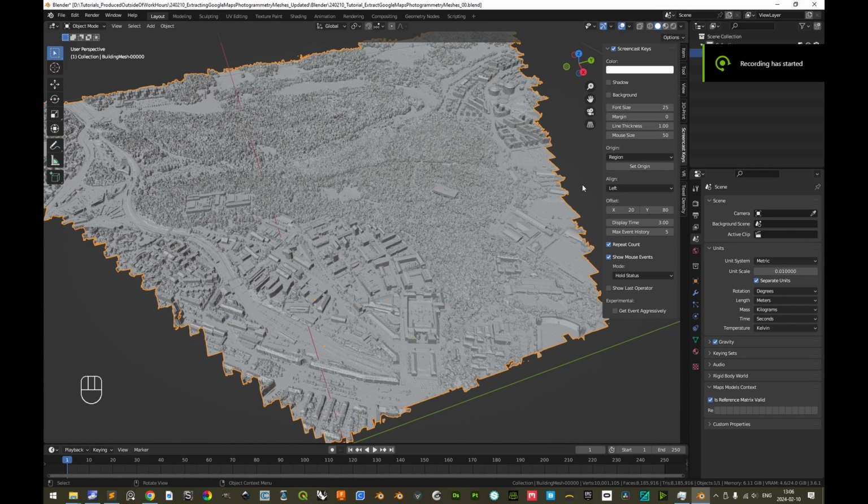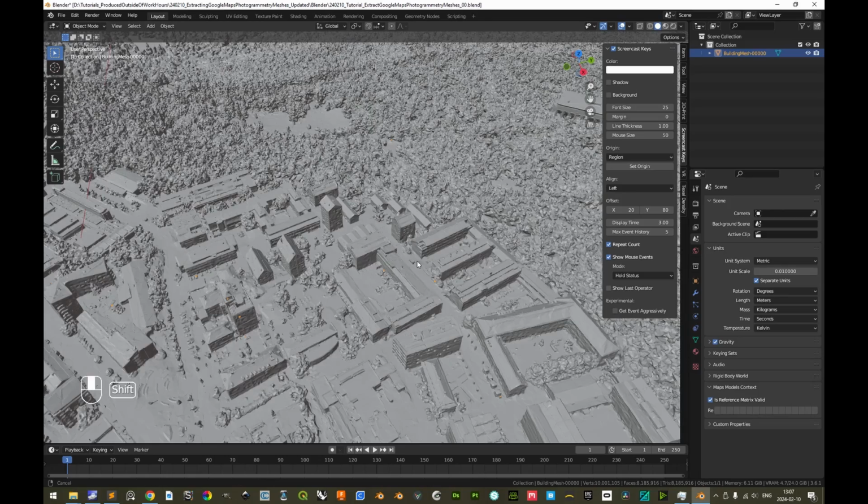So now with all of these more than 3,600 objects joined into one object, we have to take notice that we have over 10 million vertices here. This is a very, very complex scene and very processing demanding. Changing to edit mode with Tab will probably take some time. What we want to achieve is to reduce the complexity from more than 10 million vertices to a significantly lower amount by merging vertices which are so close together that the effect of merging them into one will not produce a discernible change.